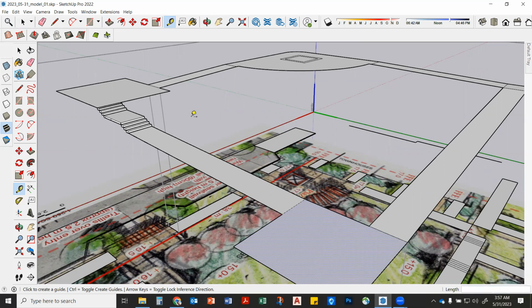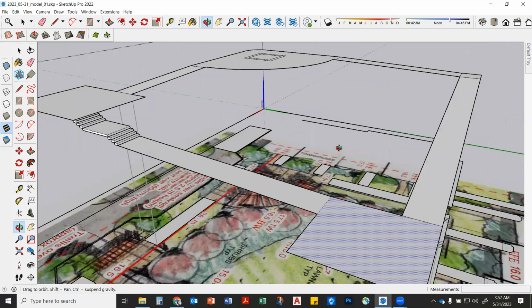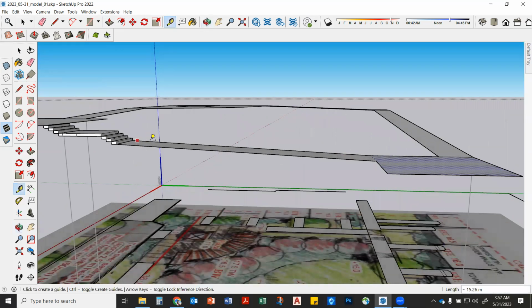All right, but look, while you're taking tea, you could make sure that you're catching up with this, yeah? If you've already built all the stairs and you're saying, gosh, this is so slow, I want to know what the slope of this walk is. I want you to calculate it. Tell me what it is. Because when I designed it, it should be less than 5%. It's not, we need to fix it.